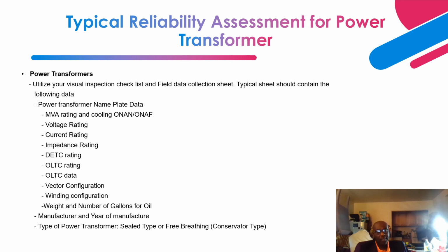What does that mean? For this tap changer, the transformer has to be de-energized before you can operate it. It usually changes the taps on the primary side for an AC-rated transformer. Usually the taps are about 5, and you see them as A, B, C, D, E. For tap A, the voltage indication is different. For B, the voltage indication is different. C usually is the nominal voltage rating. So for a 115 kV rating transformer, the nominal tap C will show you 115 kV. Tap D will have a different voltage rating.